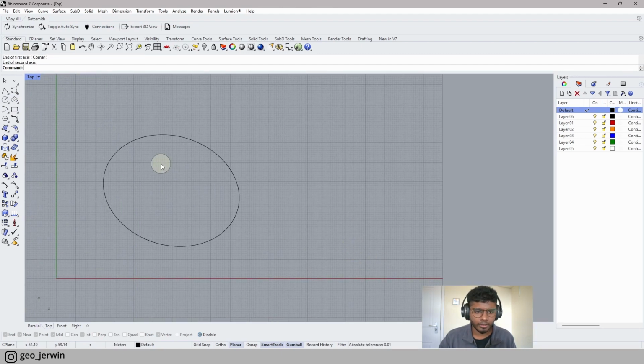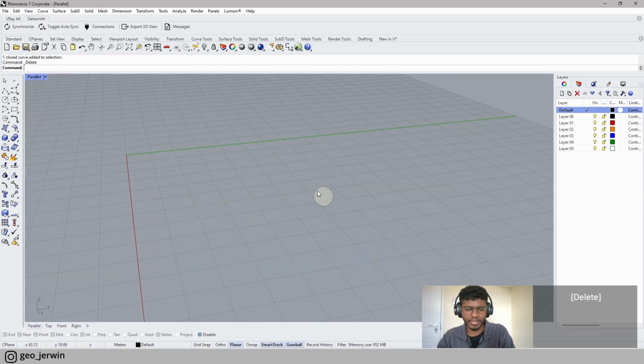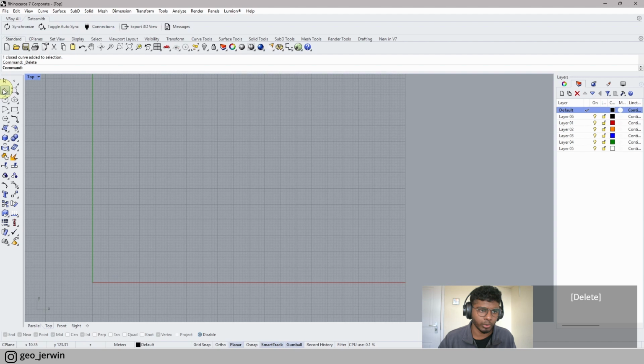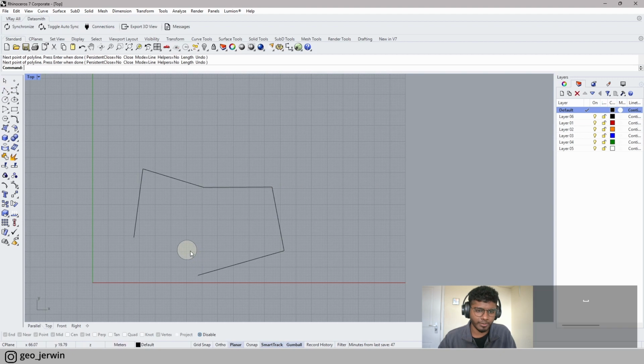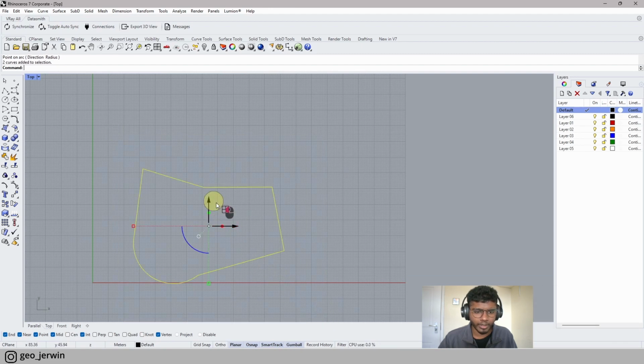And now let's say I'm just going to make a random 2D surface, or turn a set of polylines into a surface, for example. So this is not a surface, right? It's a polyline, and I'm going to complete this with some tools, for example, an arc. Again, I have to turn this snap points on to make sure my object is snapping in the right points. So there we go. I can move it like that.